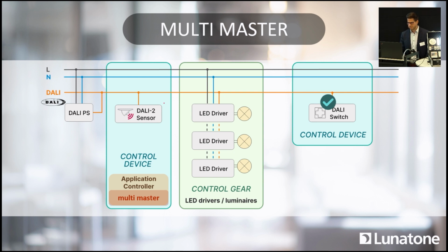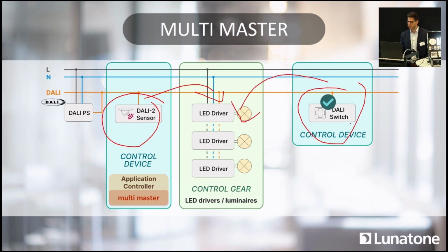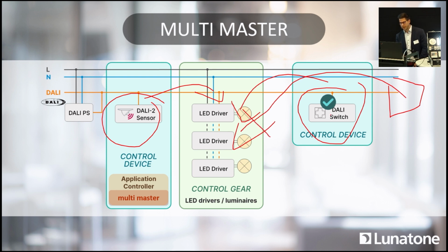So in that case, this device talks to the LED drivers, but this device also talks to the LED driver. If I would add another input device with an application controller, it would also speak to them directly. And those devices get the same command over the DALI line, but they know how to behave and how to handle it. So that's the multi-master approach.